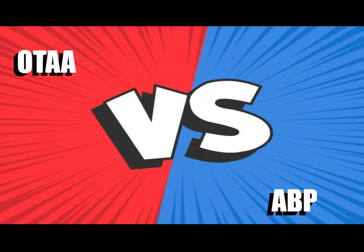So this raises an obvious question. Do I use OTAA or ABP? With care, either method can be just as secure and effective as the other. But a rule of thumb is OTAA is generally the easiest way to achieve some basic security and flexibility when it comes time to deploy. ABP is more likely to be useful in the prototyping stage where you need complete control over the activated devices. Either way, remember that unless you're doing an OTAA join before every message, you have to keep your frame counter up to date for subsequent messages to get through.